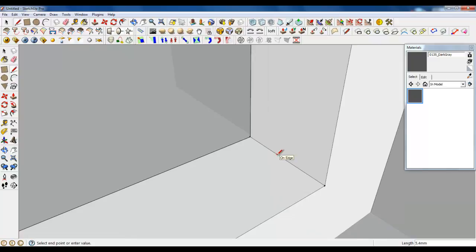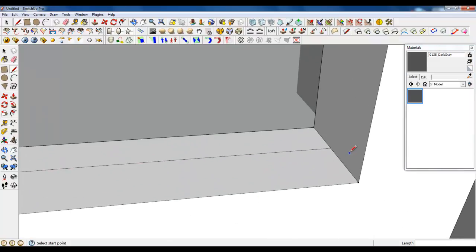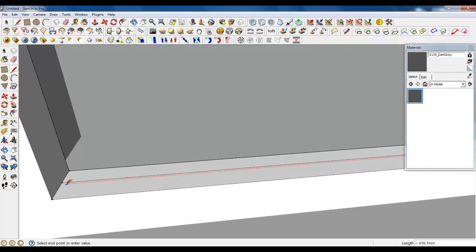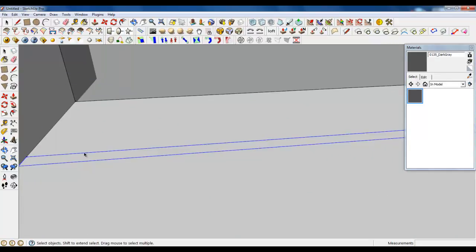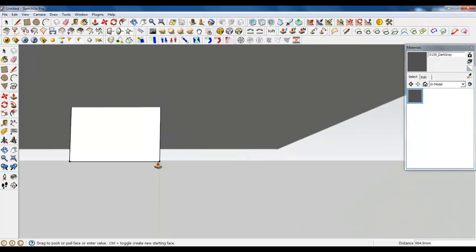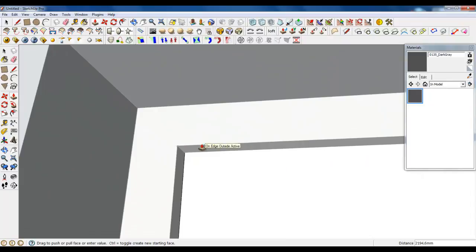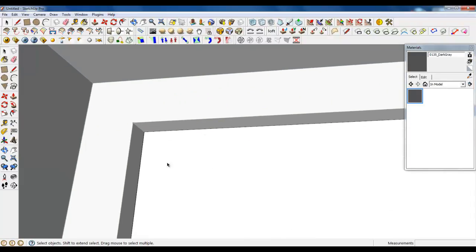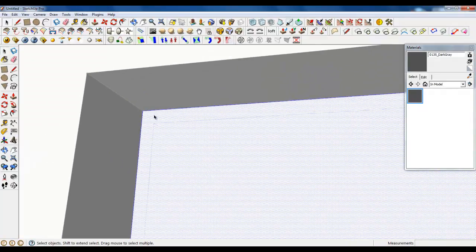Glass will be about 3 millimeters. So draw first one line and second one, and also make it group, extrude as we have done it before the window base, and this would be a glass, but let's make a rubber around the window.